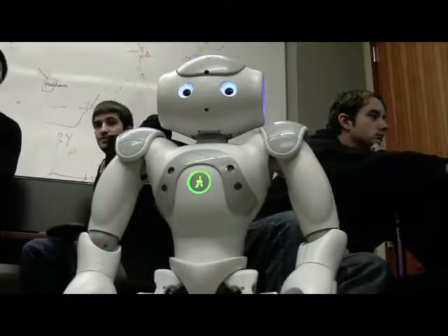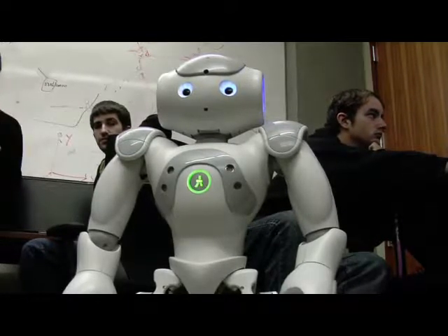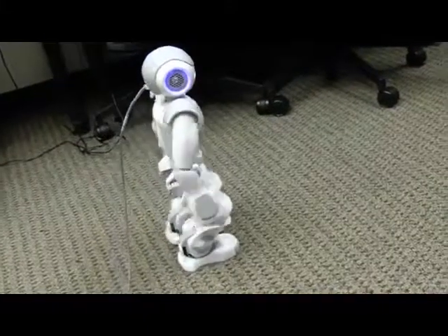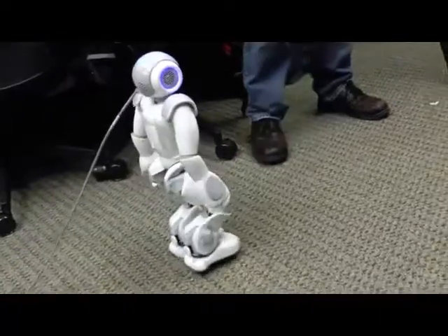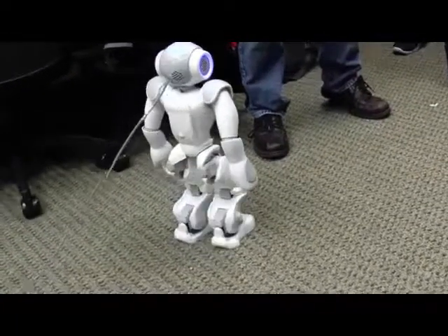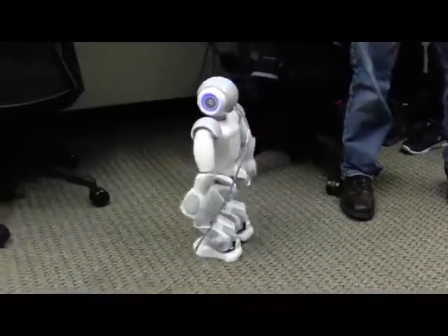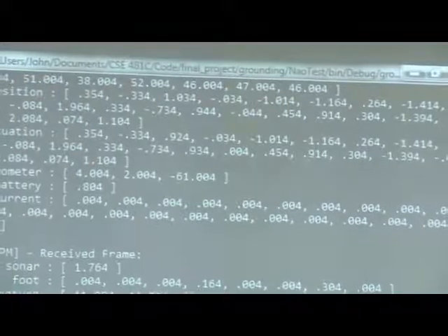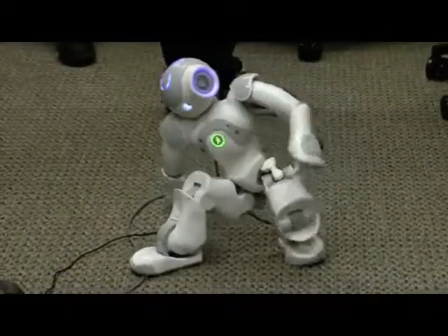For the natural language side, to interact with it verbally, we have trained a naive Bayes classifier so that given an input sentence, it understands which of its learned environment attributes we're talking about, and then it responds by telling us about what we're asking about. One of the problems with that is if we want to interact with our robot with sentences that it's not seen before, we had to have a large set of example sentences, and we used that to train our classifier.